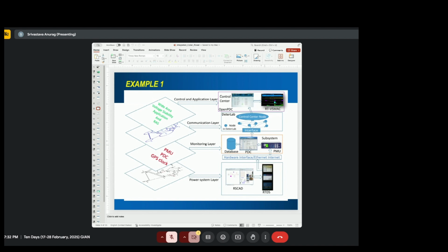Then there is a whole synchrophasor estimation process. And then if the synchronization with the GPS clock is missing or removed, then there's a PLL in the PMU, which will hold for a certain time, but after that it will be drifting. So just one sensor has a lot of details. And we had a choice: either we model it, or we just buy the actual hardware and put it here, right? So we went with the actual hardware and then integrated it with RTDS. So we do need dynamic simulation.